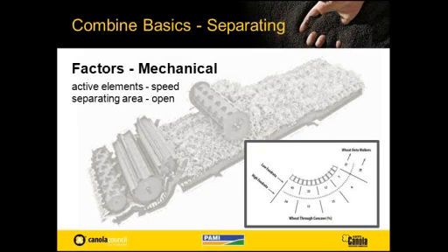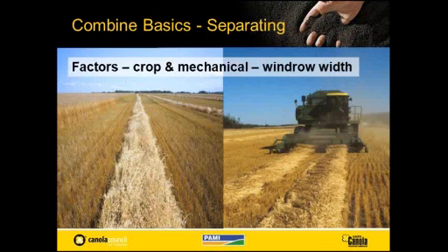And as you increase the feed rate, again, you're getting lots of clean grain right at the front coming out, but the same pattern, it decreases as it goes back. And the first one might say, well, that's because there's less grain. But you can see by the high feed rate with 38% going up onto the walkers in this particular one, that pattern didn't change, and it wasn't because there wasn't a lot of grain there. So it's important to recognize how a concave separates.